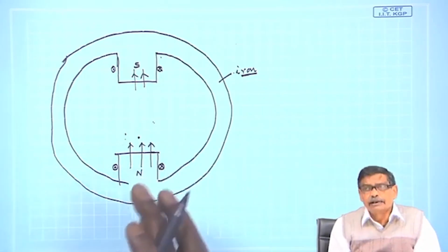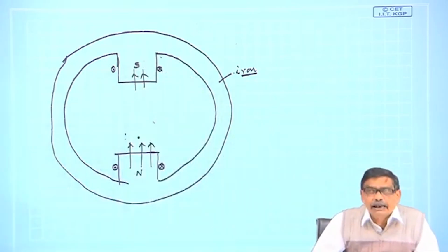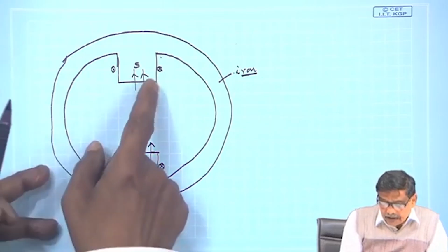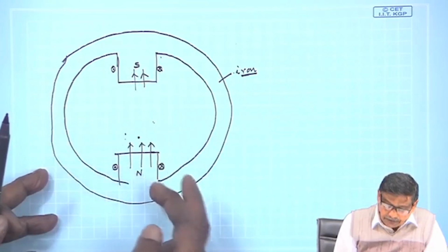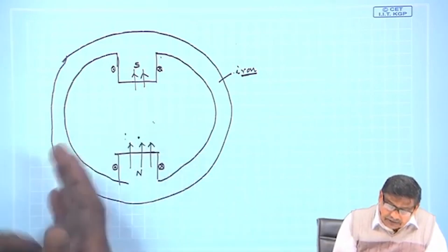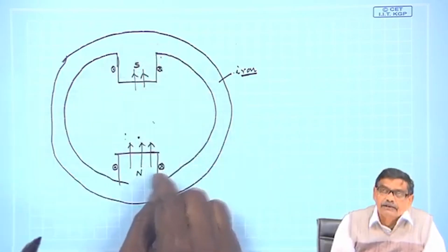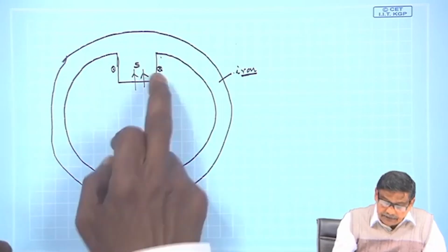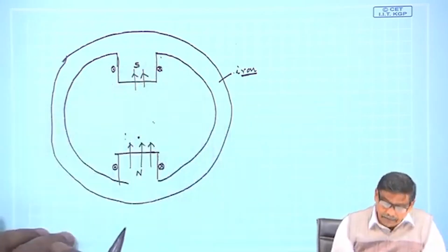So, in essence, what I am trying to tell is that these magnets could be permanent, but they could as well be electromagnets, by having coils wrapped around the projected poles and passing some DC current. Here the advantage is you can change the strength of this field by varying the magnitude of the current wrapped around it. So, this is the scenario I make.